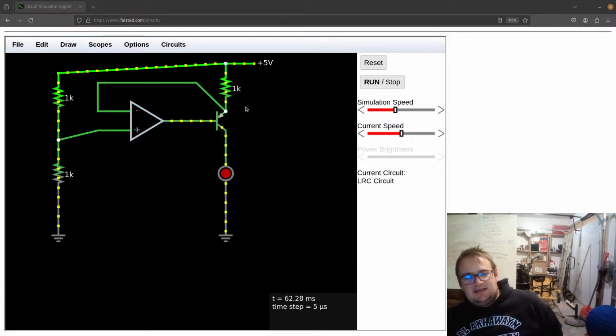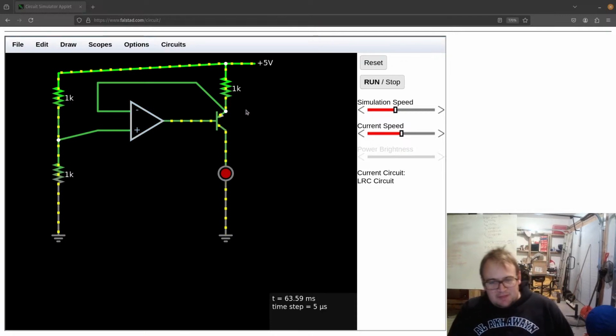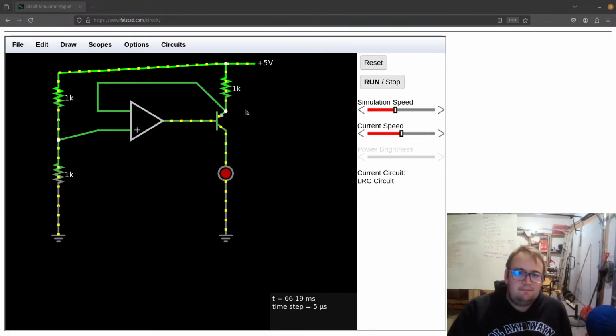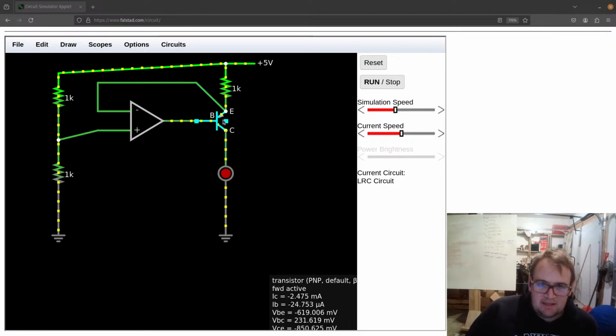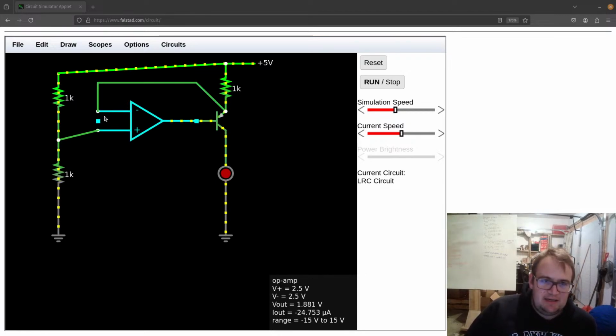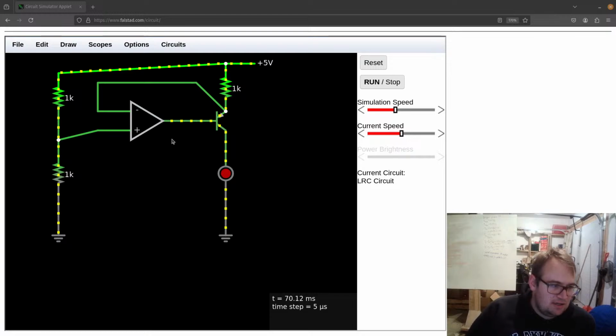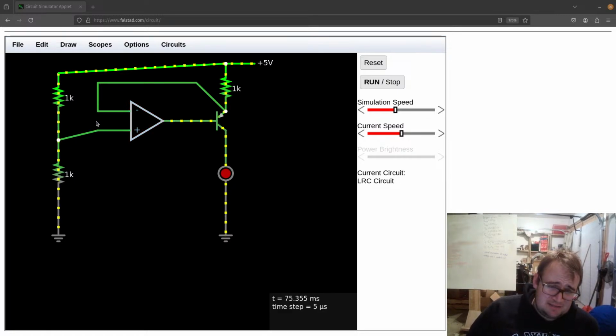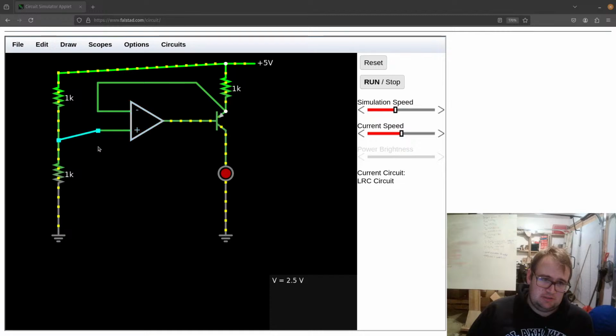You see, you just had to get the 2.5 volts up there, and then it satisfied our op amp golden rule here. Now, the other thing to keep in mind is that we're using a perfect op amp, which means that there is truly no difference in voltage here.